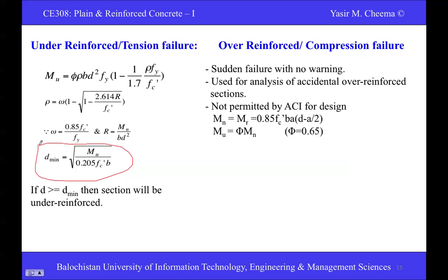अब कंप्रेशन फेलियर क्या होती है, कंप्रेशन में कंक्रीट फेल होता है, स्टील तो यील्ड कर रही है अभी, वो तो भी यील्डिंग स्टार्ट करती है ना स्टील। अब इसमें क्या है, कंक्रीट टुकड़े गिरना शुरू हो जाते हैं, दैट इज सडन फेलियर। बस आप देखें you can find so many cases, earthquake आता है whatever, स्टील नहीं टूटता, कंक्रीट निकल जाता है, दैट इज सडन फेलियर, वार्निंग नहीं। अब यूज फॉर एनालिसिस ऑफ एक्सीडेंटल ओवर रीइंफोर्स्ड सेक्शन, अब ये